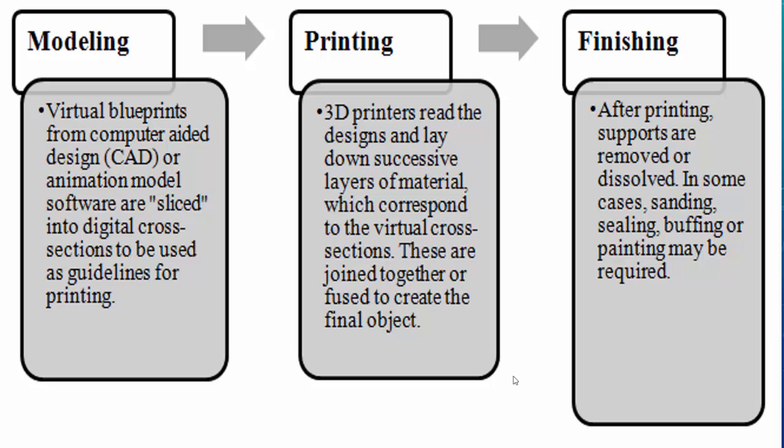Construction of a model with contemporary methods can take anywhere from several hours to days, depending on the method and size of the model. Traditional techniques like injection molding can be less expensive for many applications. Printing a slightly oversized version of the desired object in standard resolution and removing material with a higher resolution subtractive process can achieve greater precision. Some additive manufacturing techniques are capable of using multiple materials in the course of constructing parts.